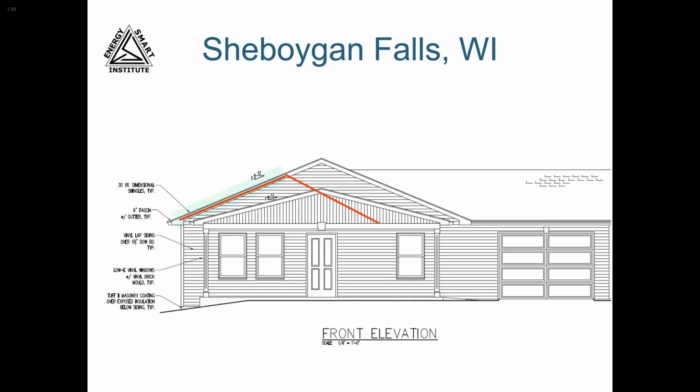And we can see that we have a true vaulted ceiling for half of it, then attic that would look like a vault from underneath, but would have attic space above for the other half of the vault. Since this is a sealed attic, the vaulted portion would be modeled separately, and the calculation of ceiling to sealed attic and knee wall to sealed attic would be a little more complex.